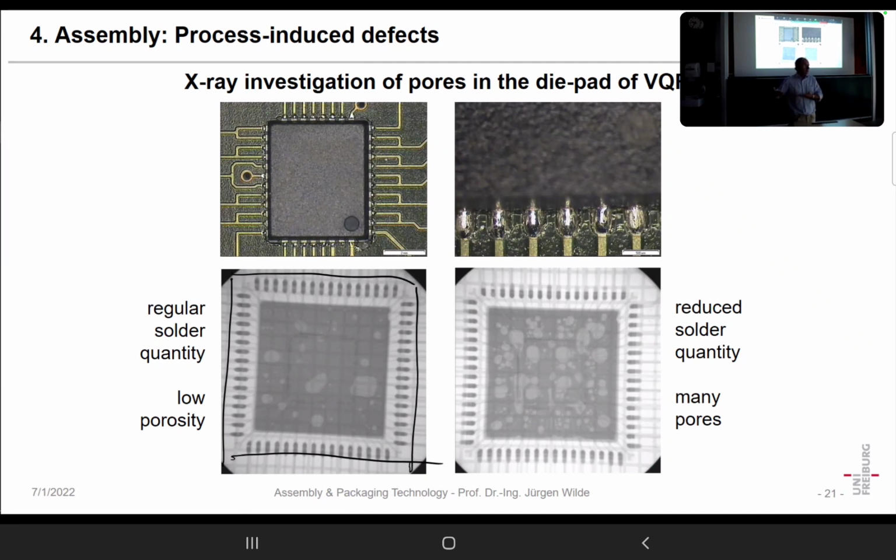The basic cause is the solder joint was bad. It had too many pores. Something interesting, which is also done in the meantime, when you have such devices, you can identify them. So if you say, okay, such porosity to the right is never sufficient, but you have a low porosity, you can take that as a fingerprint.